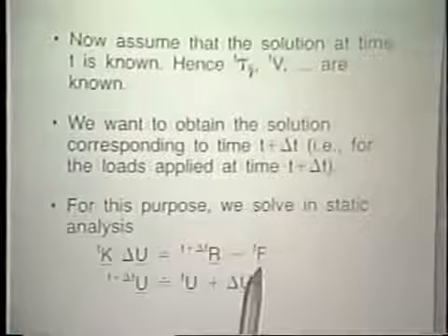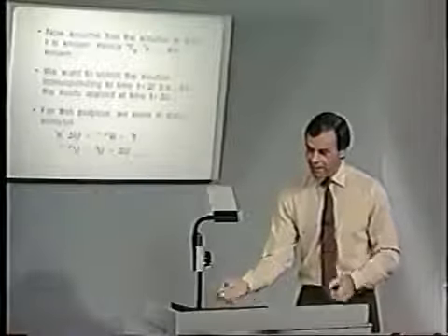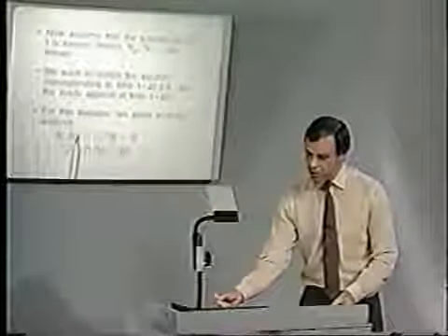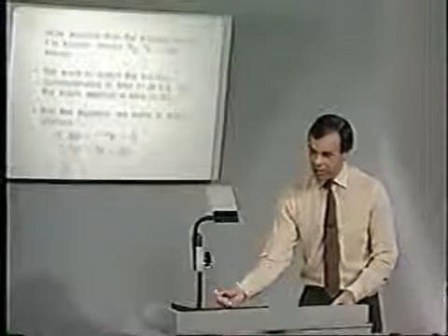Of course, there are many details involved. We will talk about the total Lagrangian formulation, the updated Lagrangian formulation, the materially nonlinear only analysis, the details that go into these formulations in terms of kinematic approximations related to large displacements, large rotations, large strains. We also will talk about the constitutive relations that enter in this tangent stiffness matrix and in this force vector, and so on. Anyway, this set of equations gives us an approximation to the displacements at time t plus delta t because of the linearization process used to arrive at these equations.